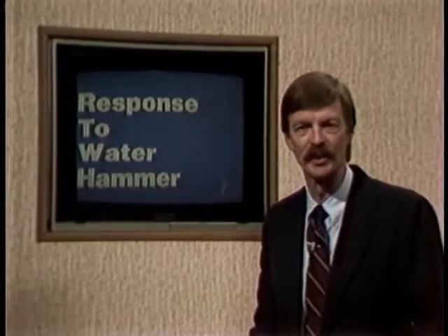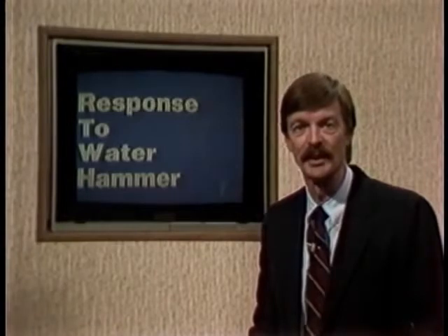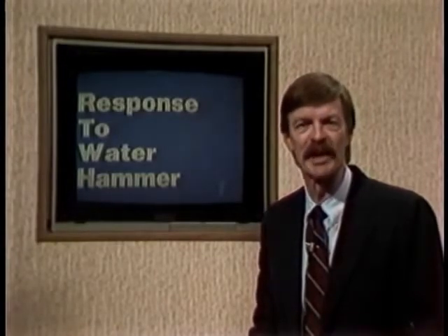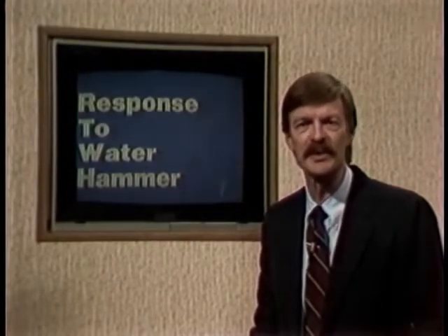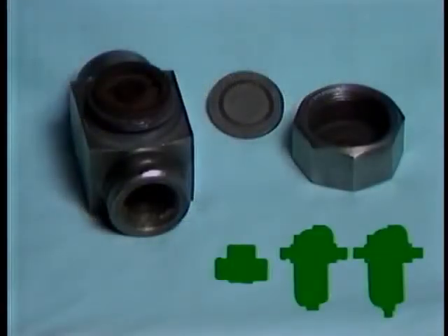Water hammer can be a very destructive force. Water, like steel, is incompressible. It doesn't give. Hydraulic, thermal, or differential shock can send 100-pound columns of water accelerating toward a trap with devastating results. Although well-designed systems minimize the occurrence and severity of water hammer, its effects on a trap's performance must be considered in many situations. Traps that are designed to resist these damaging forces are recommended where water hammer is likely.